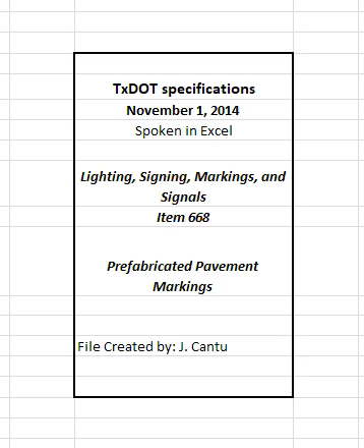3.6.1 Adhesion. Ensure markings do not lift, shift, smear, spread, flow, or tear by traffic action. 3.6.2 Appearance. Ensure markings present a neat, uniform appearance that is free of excessive adhesive, ragged edges, and irregular lines or contours. 3.6.3 Visibility. Ensure markings have uniform and distinctive retroreflectance when inspected in accordance with TxDOT 828B.